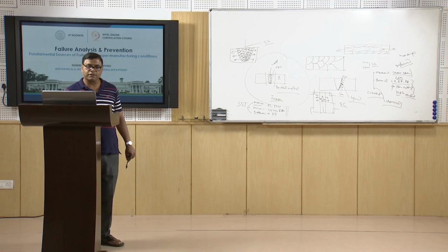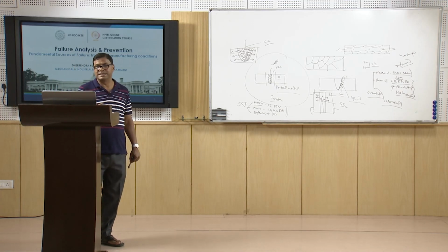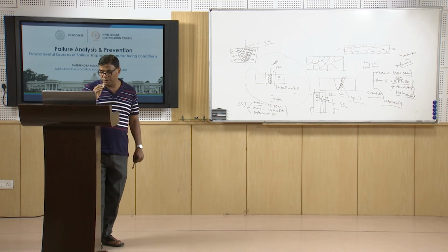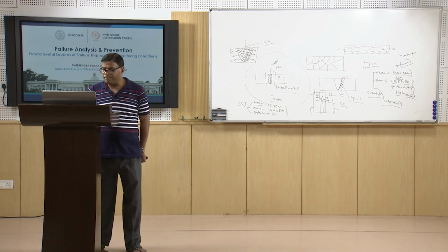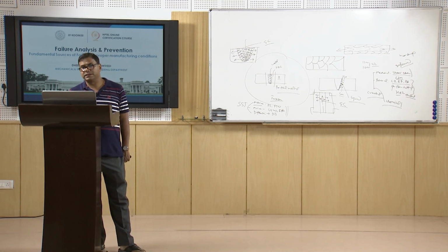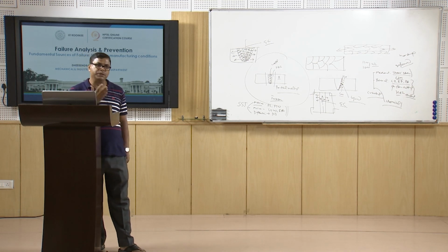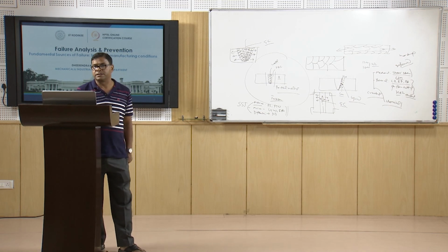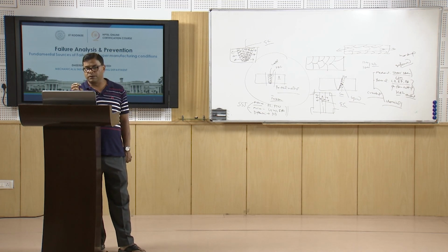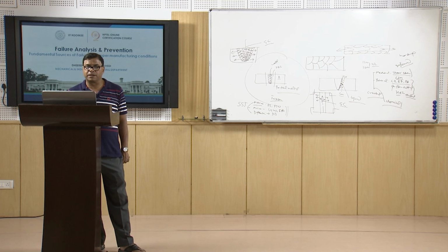And another undesirable feature, especially for the steels which are produced by cold forming or cold working based processes, is that it will lead to an increase in the ductile to brittle transition temperature. So, for those components which are to be used under low temperature conditions, it must be kept in mind that their ductile to brittle transition temperature is within the safe limit, as a cold deformed, cold worked component can fail due to a high ductile to brittle transition temperature.